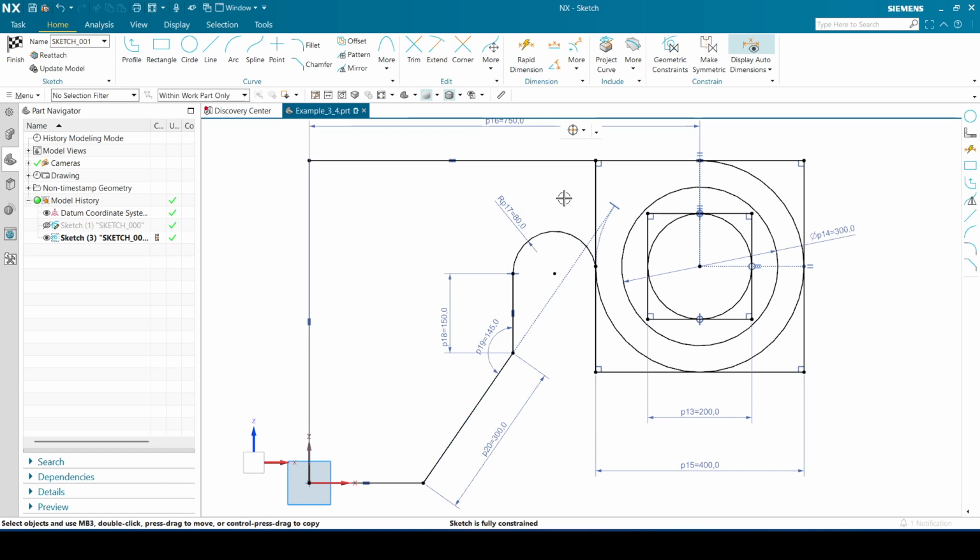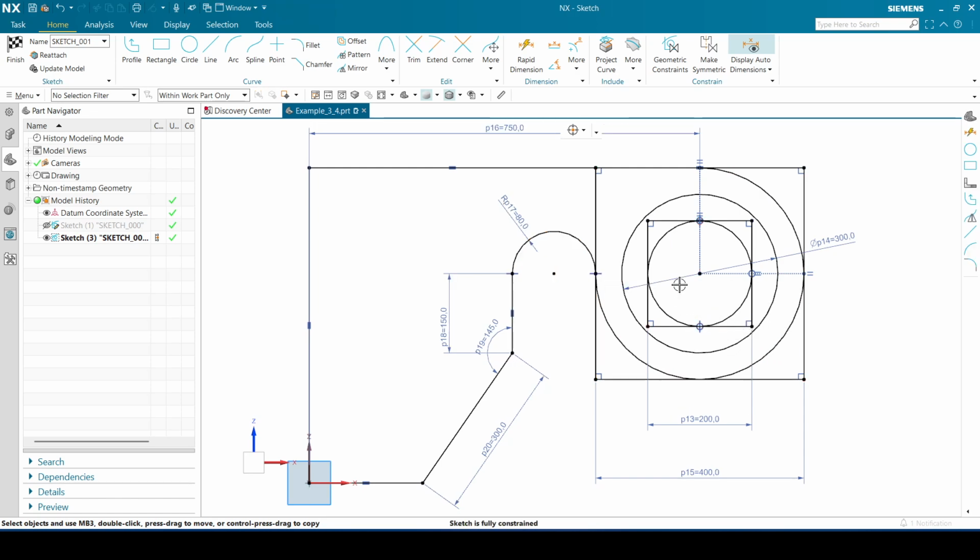So last year, a lot of students who came very close but had a mistake, their mistake was they had this incorrect. So let's quickly delete this one. What they rather did was they had this tangent to either this or this, which is the same because this, since it has the same radius and meets in the middle, is implicitly tangent to this edge. So if you put this tangent, it looks very similar to your reference image.